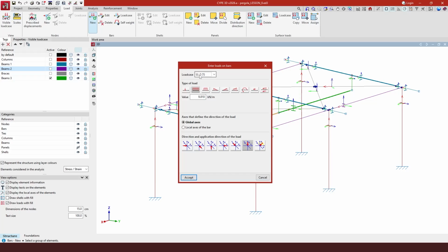It's also going to be attached to the same load case, position 1, point load of 10 kilonewtons, also applied in the middle of the bar, 0.5, and this time we're going to select that it's going to go in the positive direction of the x-axis.